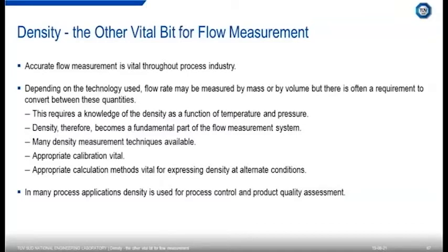But again, it's important that you use the relevant ones. And there are a range of techniques for calculating densities of gases and gas mixtures. Again, it's important to be able to measure the composition if it's a mixture and understand what the limitations are of the various equations of state and which are the best to use for particular applications.